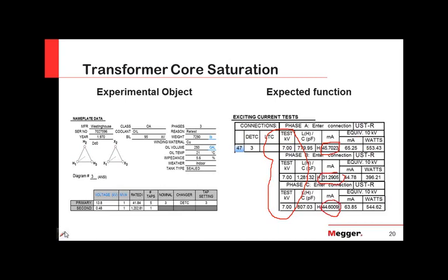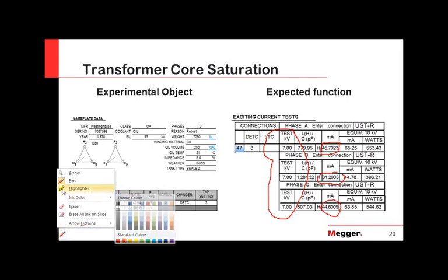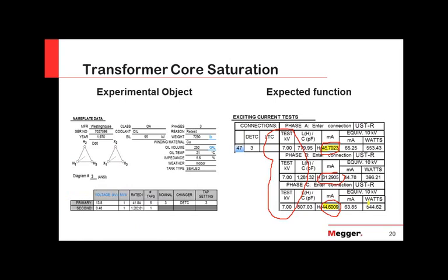One thing that I would like you to remember is that one of the important things you have to take into account is that the values that you see on the external legs or external limbs of a core type transformer should be very similar. That's what we call the symmetrical phases inside the transformer. Anyhow, as you can see here, these two numbers are very close. The error between those two is below 2%.